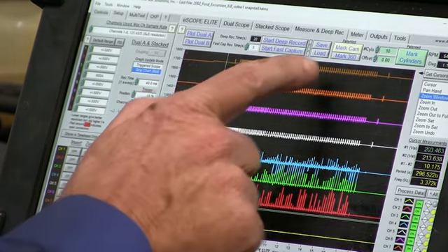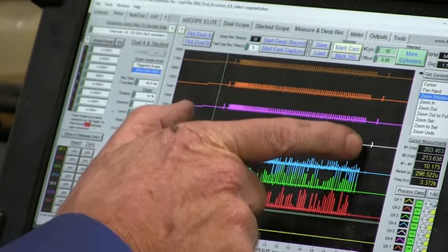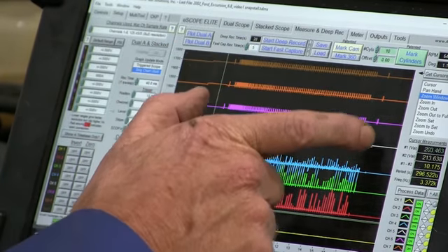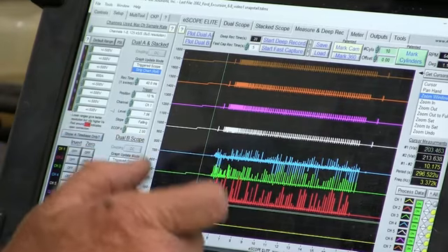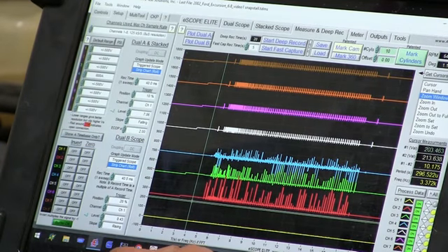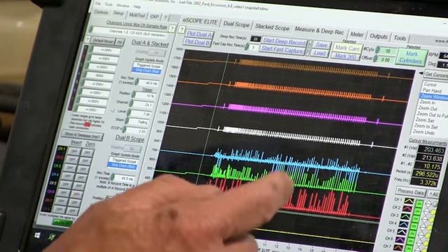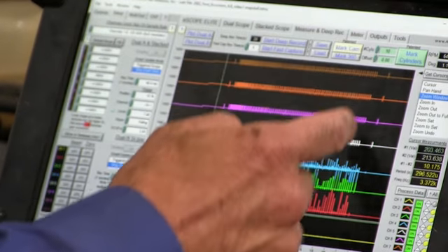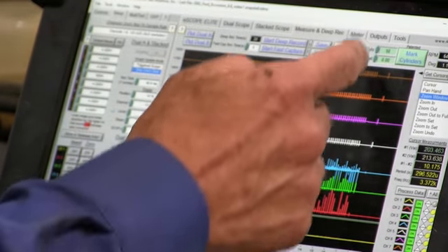Okay, do you see how the injectors were just shut off and they just barely started to come back on? Now guys, this is to reduce the torque output from the engine so you don't burn up the tranny. Think about this as an engineer. The engineer is worried about the tranny slipping, and the only way he has to see that is the input speed against the output speed sensor of the tranny. The only thing he can do is to limit the torque. So this is the torque limiting. That's commanding a torque limit.